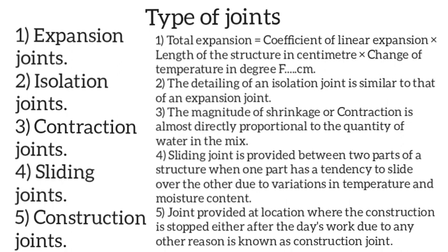When such tensile stresses exceed the tensile strength of concrete, it results in formation of random cracks. Contraction joints are installed to allow for the shrinkage movement in the structure. In general, a building continues to dry out during its lifetime, and as such dimensional change due to shrinkage should be taken care of in its planning and detailing.